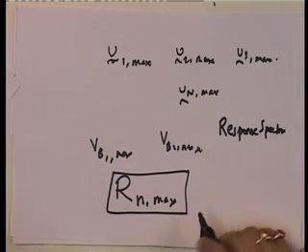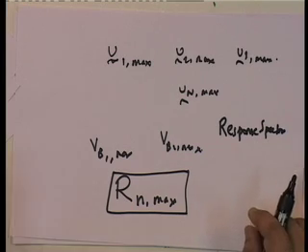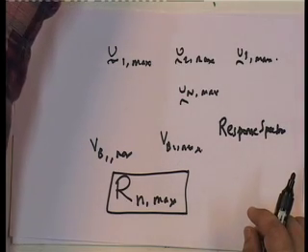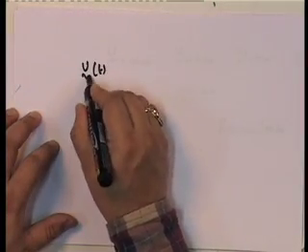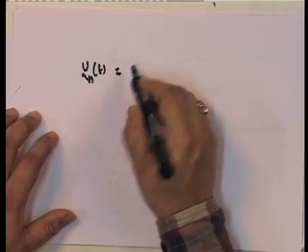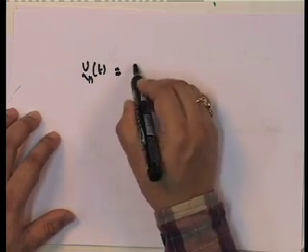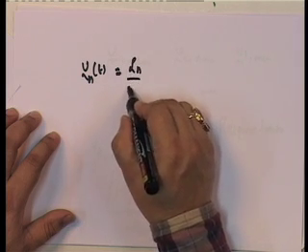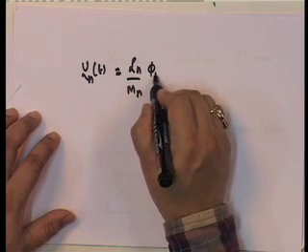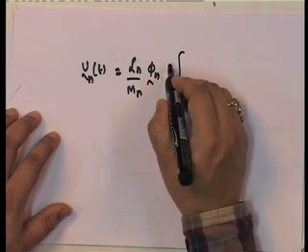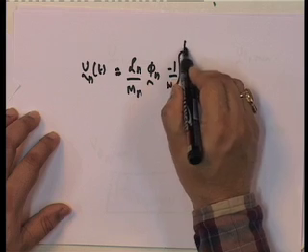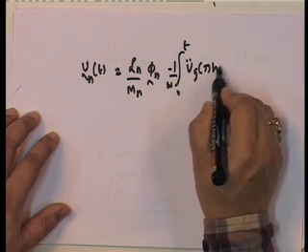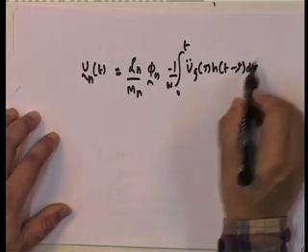Okay, if I was using the time history, and I found out, for example, let me just go back here, if I was looking at time history, Vn of t would be equal to Ln upon Mn into phi n into minus 1 upon omega, integral 0 to t, vg(tau) h(t minus tau), which is the unit impulse response function.